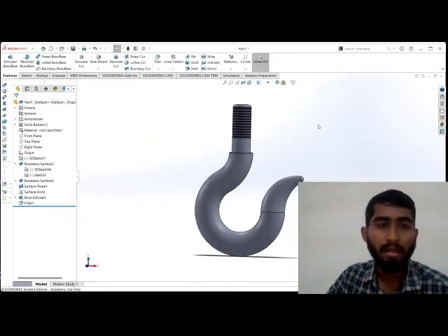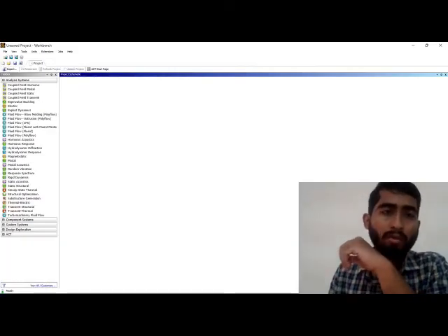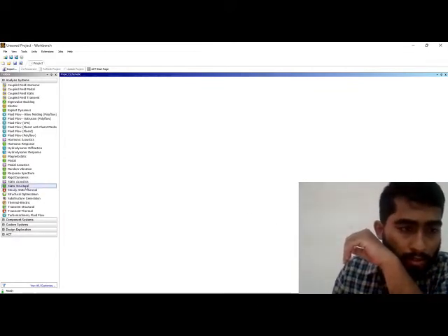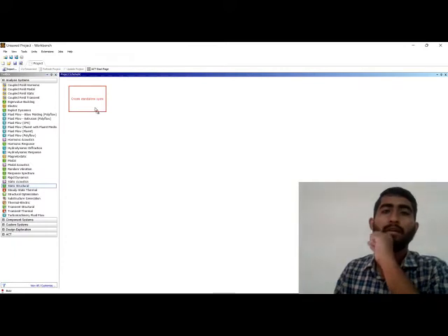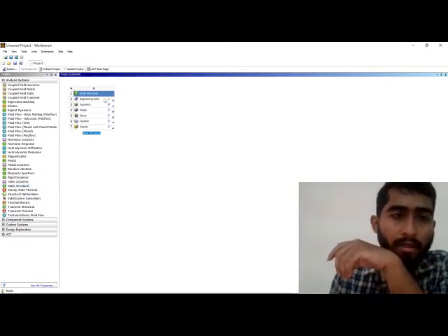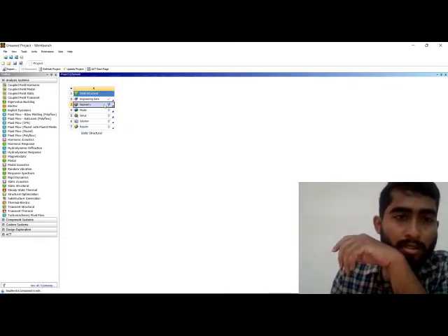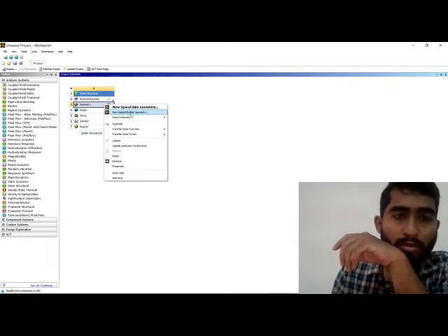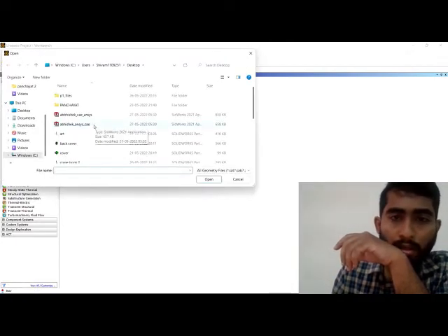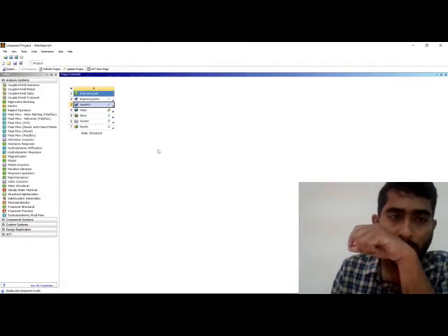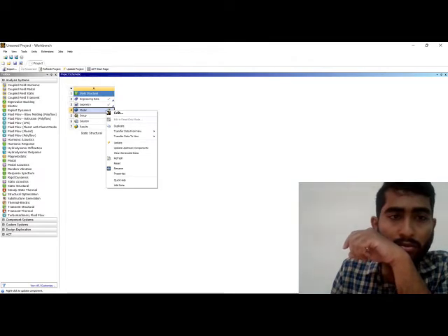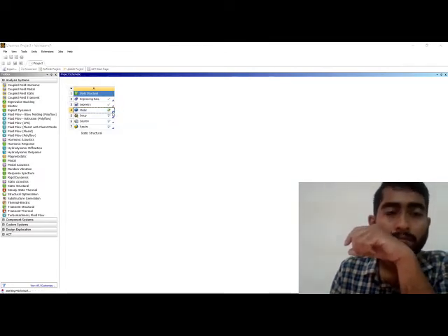Next we will see the analysis part. So moving on with the analysis part, I've opened the Ansys workbench. I click on static structure because we are to do finite element analysis. The engineering data is already there, so I'd like to now import the geometry directly. Import geometry, browse. Here it is. I've got the tick mark here, so I'd like to now edit the model.